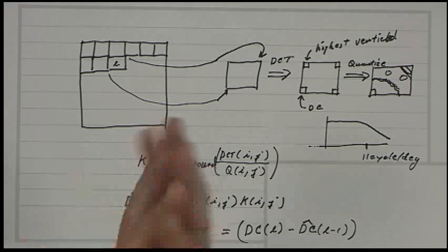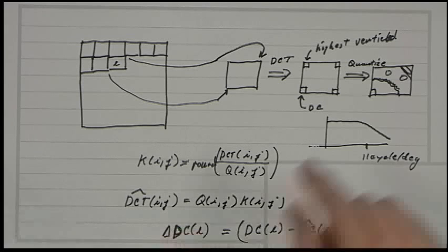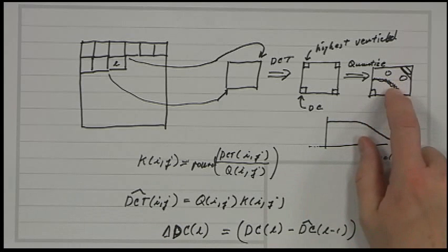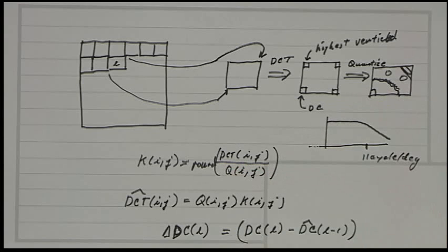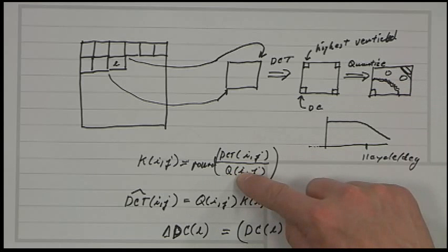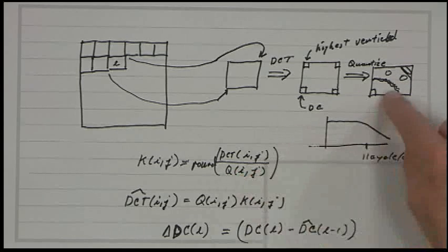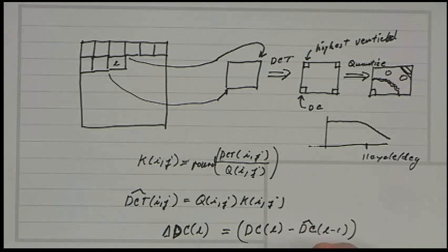But presumably the reason you sampled at the frequency you did is because you thought there were some frequencies there, and they may not be as large in magnitude, but it doesn't mean they're not important. So there's information there. They're not all going to go completely to zero. I'm oversimplifying. It depends on the size of the quantization level. Even if you have a large quantization size, if you have a very strong signal, it'll be enough to get some output.